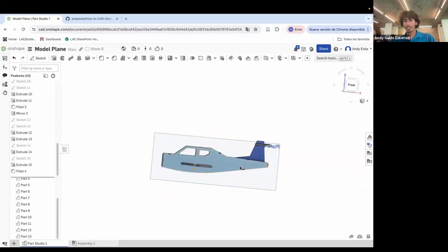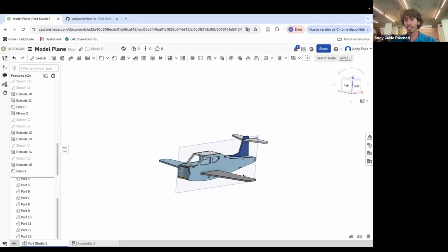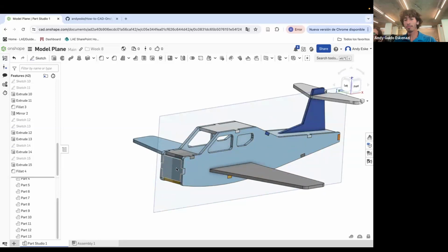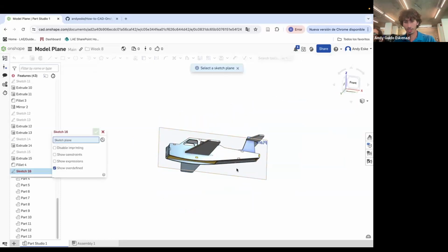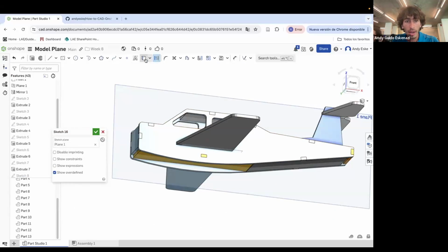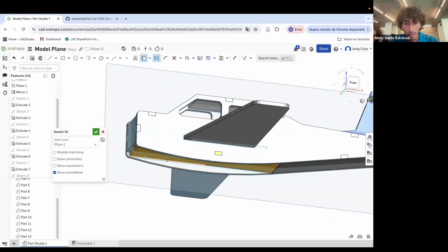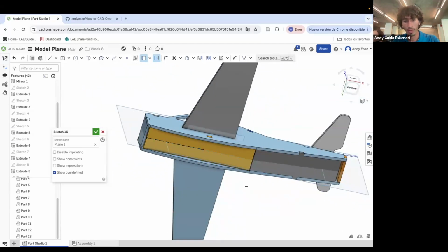so now the last thing that we're gonna do, what I didn't do on my other design, is maybe we could add the stand. We're gonna imagine this one doesn't have one. It's like a glider, but let's do the stand. And this is where we can get creative because we can do a sketch here on this face, and I'm gonna convert entities this entire line in here. Good.